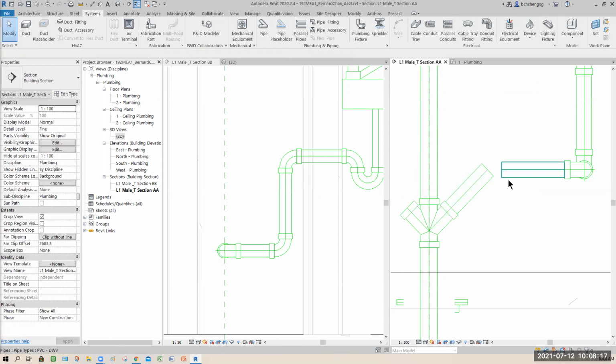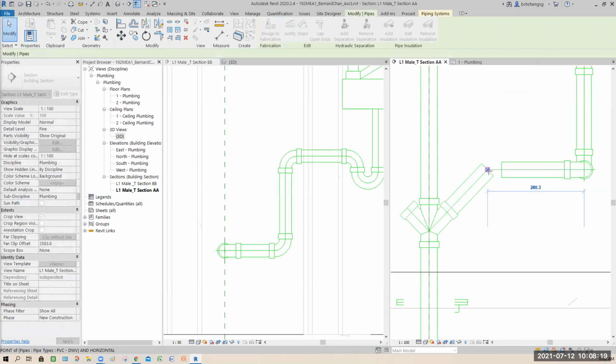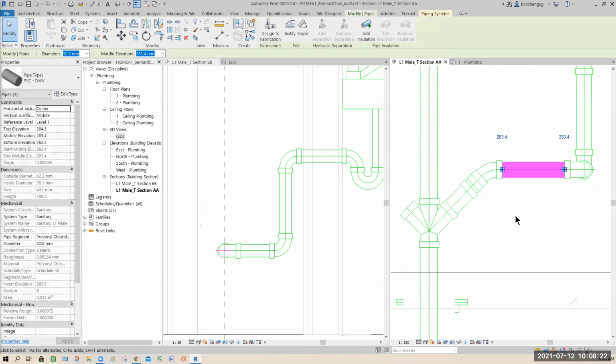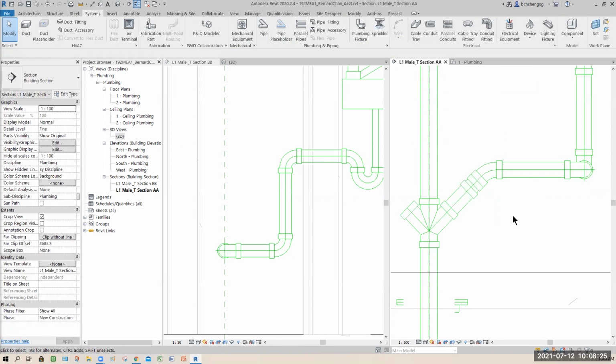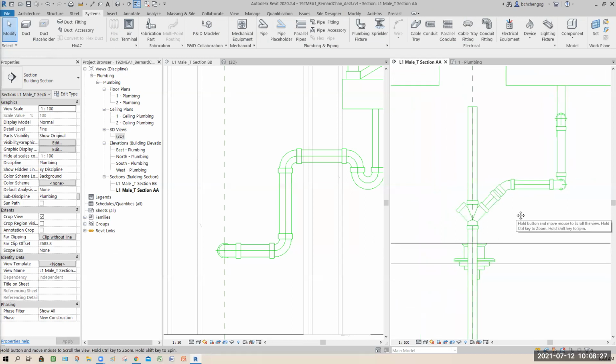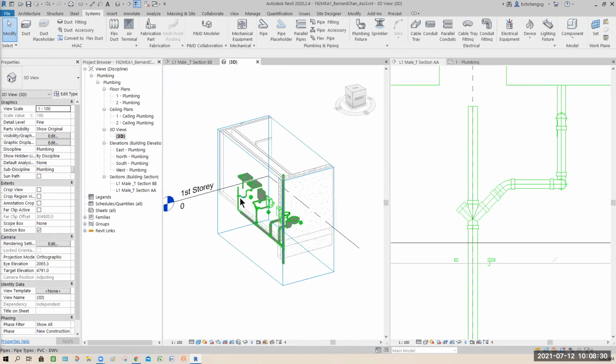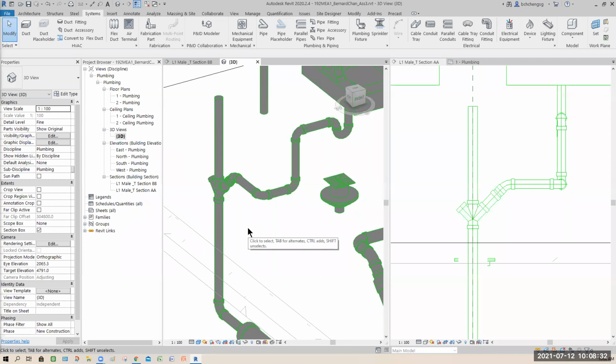Okay, so here, hopefully when I drag and join, it should, good. See that? Okay, so done. 3D. This is how it looks like. You see, too many joints. As I say, as far as gravity is concerned, the leak is minimal, but for pressure pipe, try not to have many joints, normally. Because you give the chances of leaking is higher.